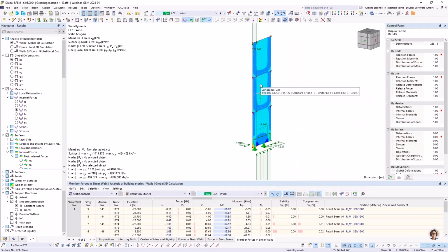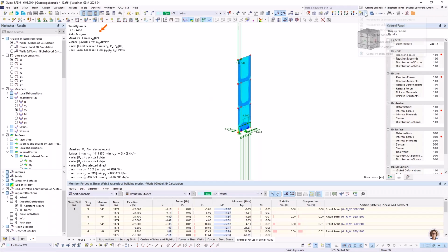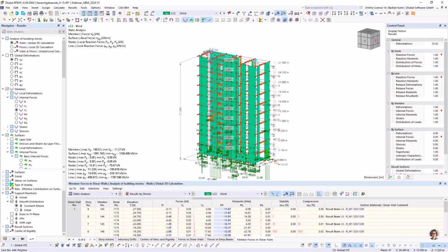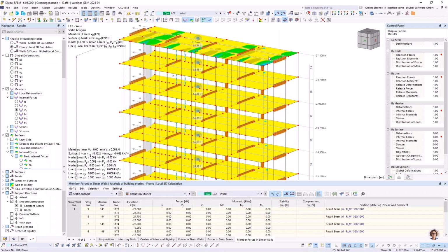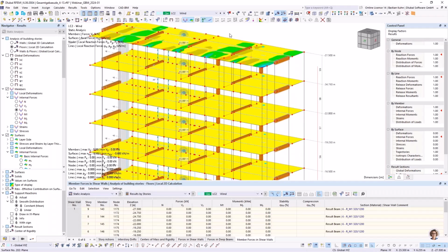Yeah, this is the advantage. Let me take a look. I probably have missed some points, but I can't remember them now. Yes, one thing. If we cancel the visibility mode and take a look at the floors again, you see also an effect. nxy in the floors is nearly zero, even though I have such a high horizontal deformation. Why is it the case? Because I'm calculating only 2D for vertical approach in this here. And if I go to walls, it's different.